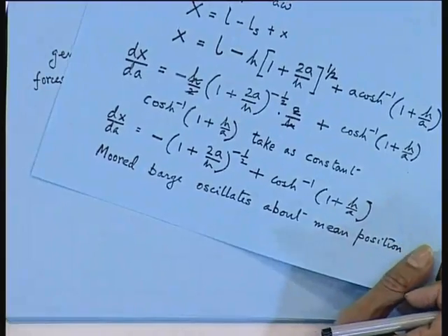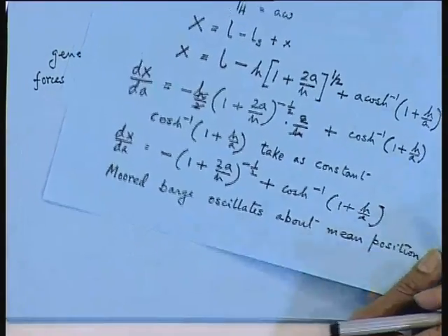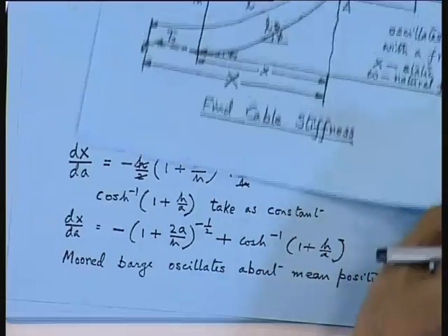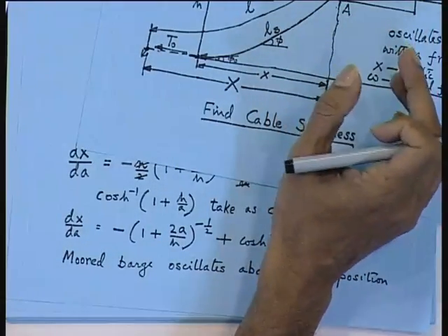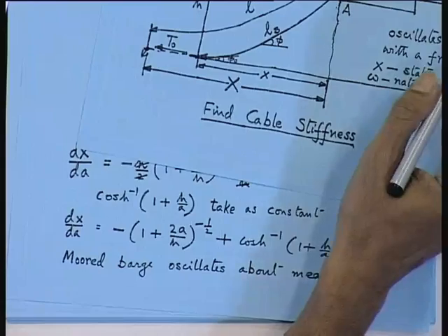So what I was talking about, we have found out the dx by dA term. Of course, we have made a simplification, and this is just one equation. Say we are trying to calculate this in surge, but similar equations you have to do for surge, sway, heave, pitch, and not only that, all these motions are going to come together.